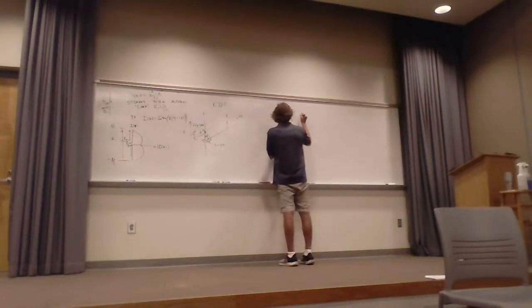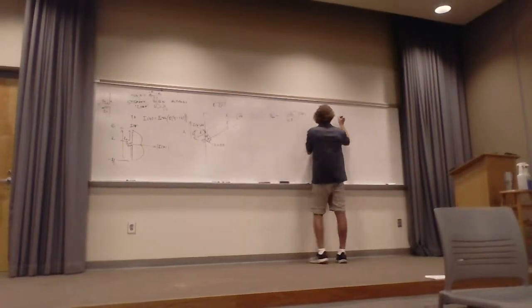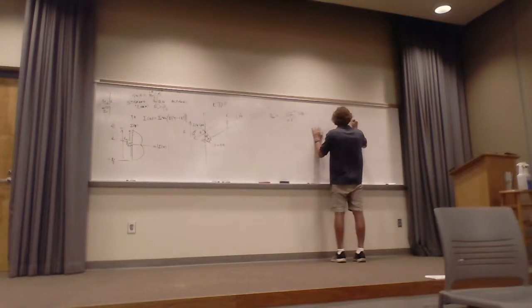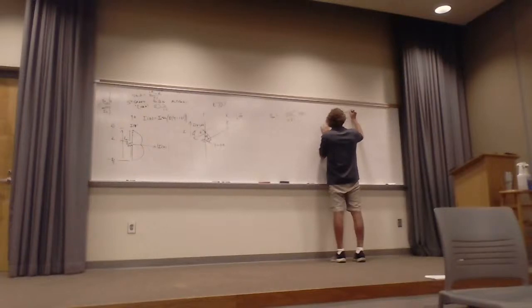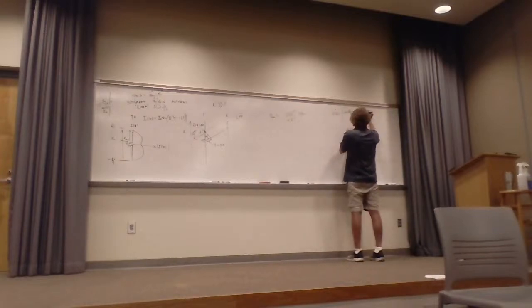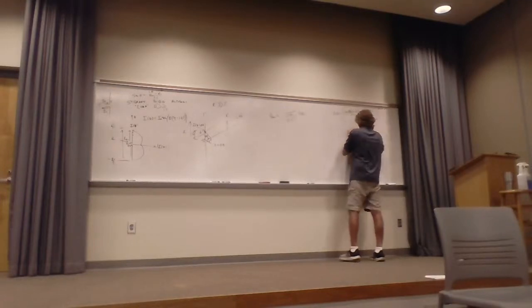And then it's going to be times F theta right there. But his F theta is equal to the ones we got for E and H squared. So it's cosine of beta L over 2 cosine of theta minus cosine of beta L over 2, divided by the sine of theta, and it's squared.